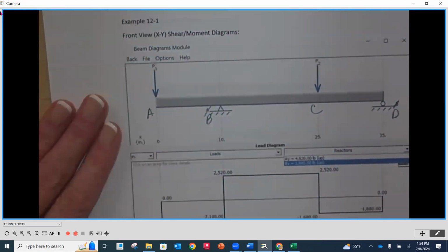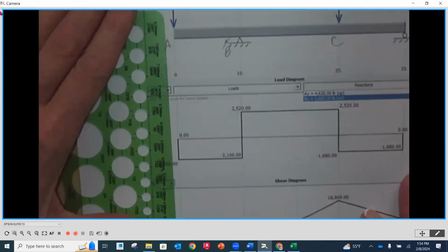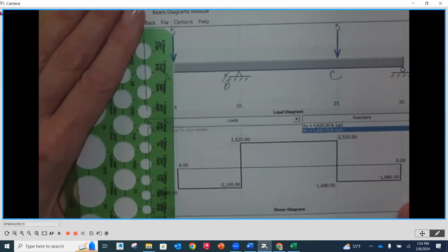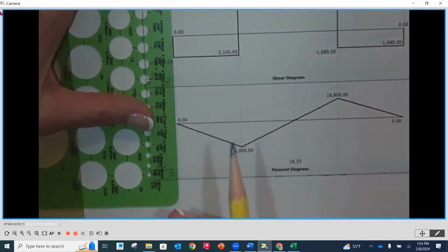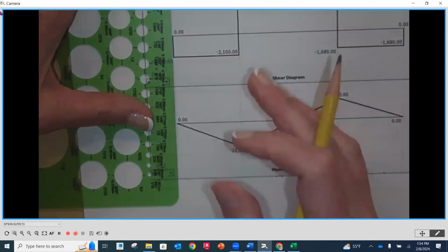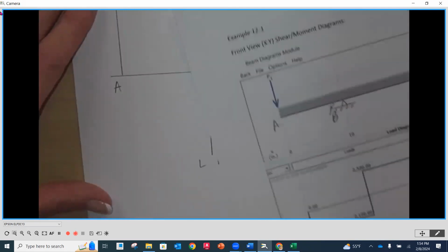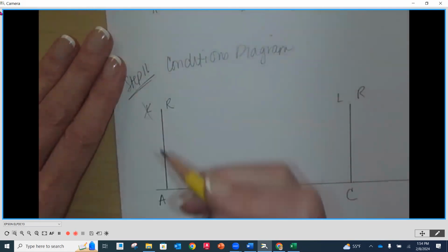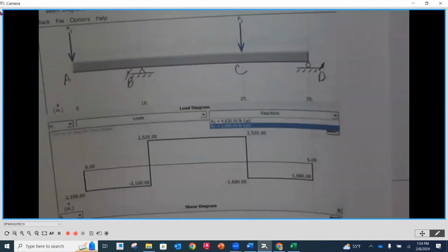So now as we look here and we go down, this is all in projection, shear and moment diagram wise, right? Do you notice on A here that as I go down, I only have on center shear on the right, and we're going to say no moment, but there's only something starting on the right of that center line? Do you see that? Yeah. So there is nothing to the left. All right. So on point A, it just means that we're not going to be worrying about that left side. Okay. And we can say the very same thing for point D as well.